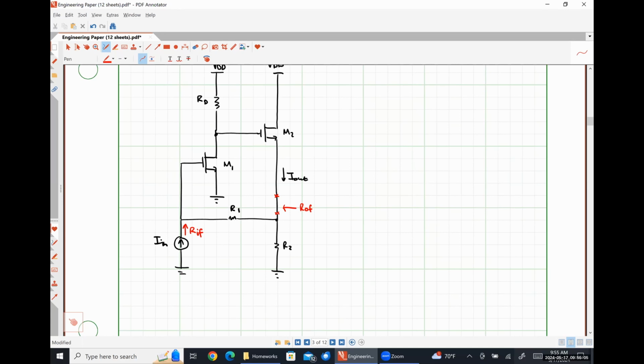That's the principal difference that we're going to see whenever we're looking at a current connection. Whatever we see up is in series with whatever we see down, because we're dealing with a current, whereas when we had a voltage, it was whatever we saw up in parallel with whatever we saw down. Okay. All right. So what is our feedback network going to look like here?